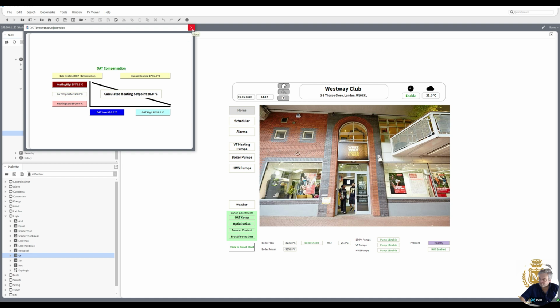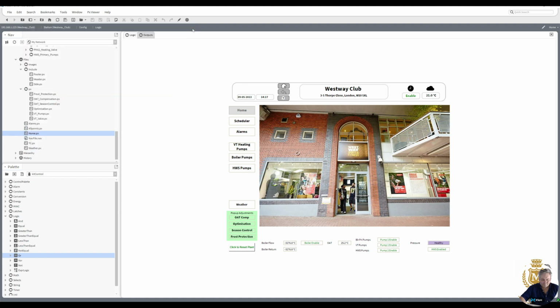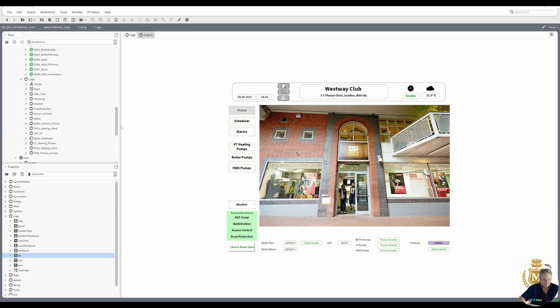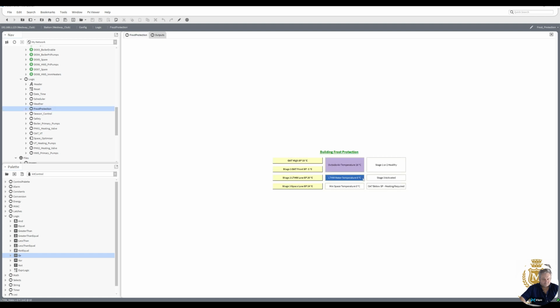They're not using outside air compensation, are they, for the temperature? Really don't need that. Outside air below set point heating required. That's because I overrid it. Heating is off.